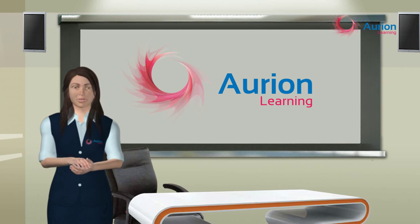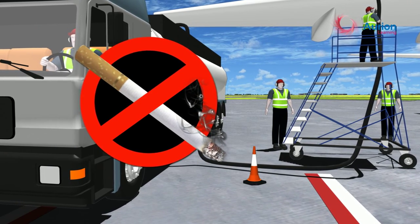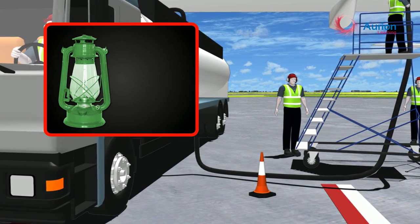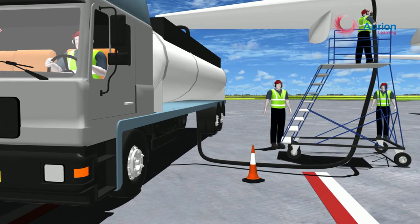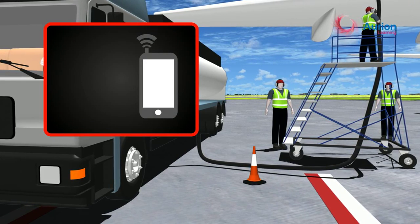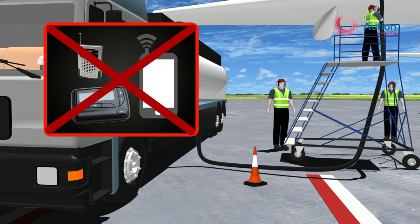Due to these inherent risks during refueling and defueling, certain general precautions need to be taken to avoid a fire hazard. They are: 1. Do not smoke around an aircraft during fueling. 2. Open flames such as oil lanterns, candles or matches are prohibited. 3. Do not use portable electronic devices such as mobile telephones, portable radios and pagers during fueling activities.